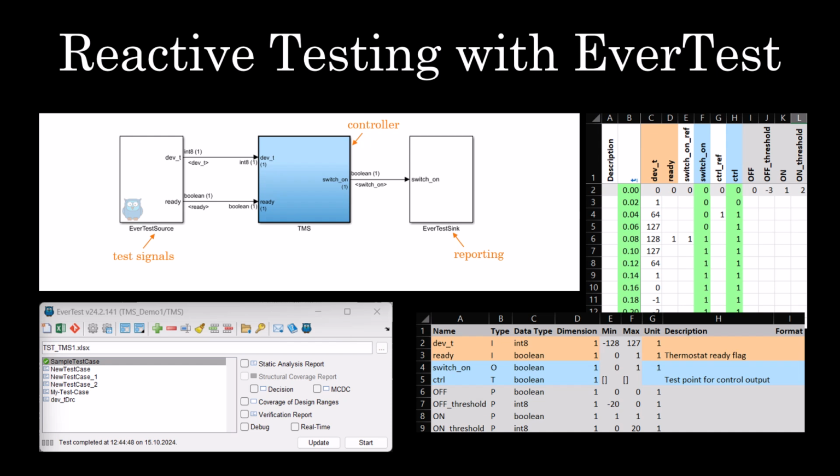EverTest also supports more complex test scenarios. You can define a bypass signal in the interface sheet of the test specification. Just use the IC type instead of I type for the related input. The C stands for closed loop simulation. After update in the EverTest user interface, you will receive a bypass signal for the EverTest source block. Now you can provide an external input signal which will be reused in the test case. The bypass signal will be grayed out and documented in the final EverTest verification report.